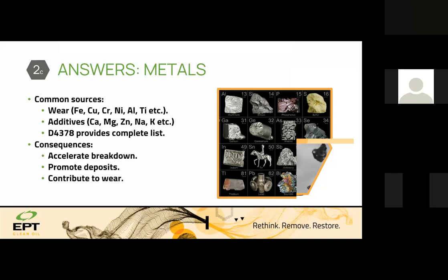First, I get the baseline sample, and then I look into the used oil analysis. Whenever we are monitoring the wear elements, we see how much breakdown is happening in the machine, and then we need to look at the additive consumption.